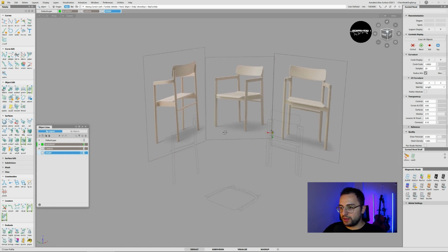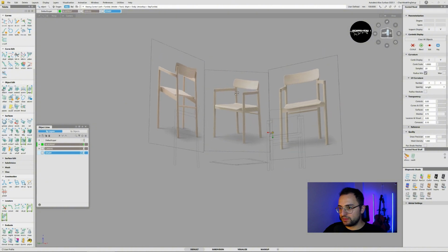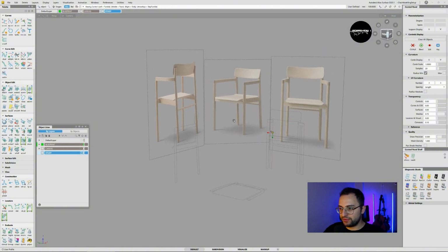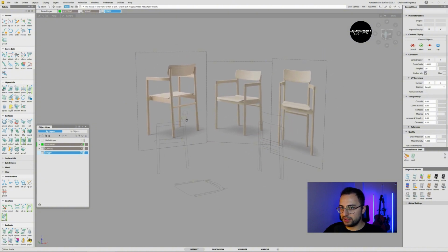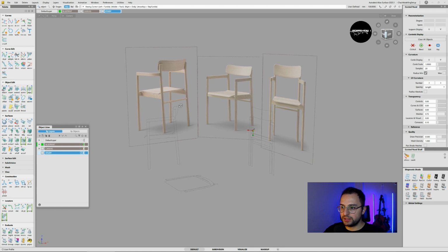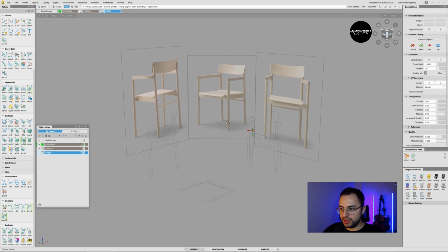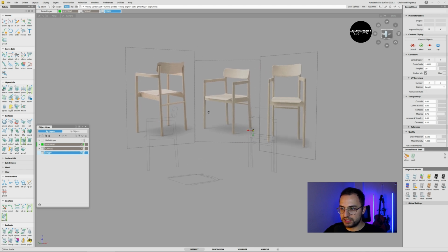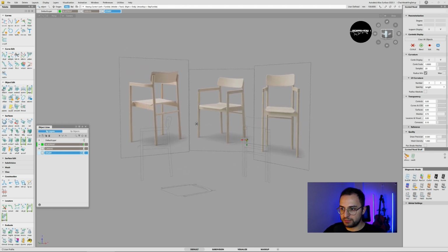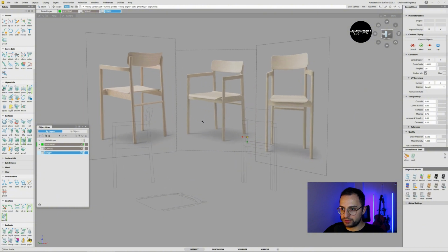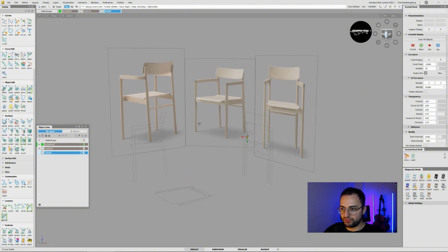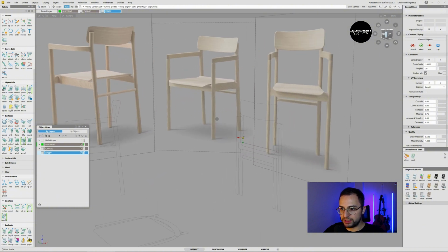Yeah, let's begin with, I guess, rotating the screen first. If you are coming from the beginner series of mine, you know most of the stuff, but just to be clear, we can repeat them. Shift and Alt key and left mouse button rotates the screen, middle mouse button pans, and right mouse button zooms in and out. This is how we find our way through the empty space.